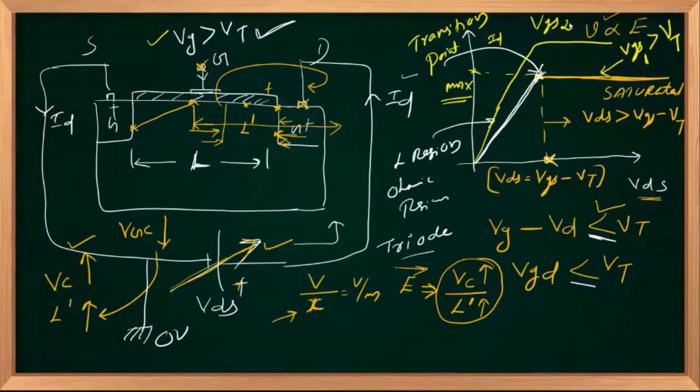So if you are increasing or decreasing your VGS, you will have a family of curves. And that is for VGS0, VGS1, and VGS2. It's obvious that VGS1 is greater than VGS0 and VGS2 is greater than VGS1, because you have larger drain current, implying a larger number of carriers. The more the gate voltage, the more carriers, and the more current.